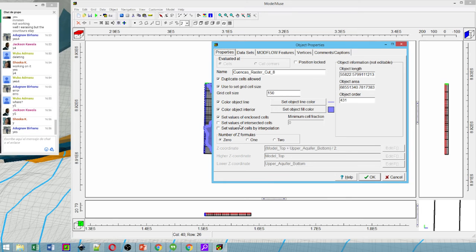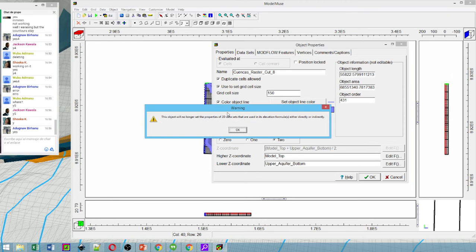Cool. And here you're going to change the number of set formulas from 0 to 2. And this is a warning. This is not a hero. This is actually a warning. And warning is just something that you have to take into account. But it doesn't mean that you have done it wrong. If you have done it wrong, it will say error. But a warning is more like a feedback, something like that. Okay, and this applies for every stage of the model, because many times you have warnings, but you have to know what the warning is about.